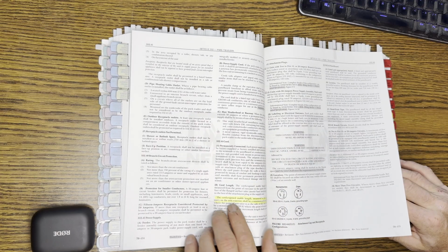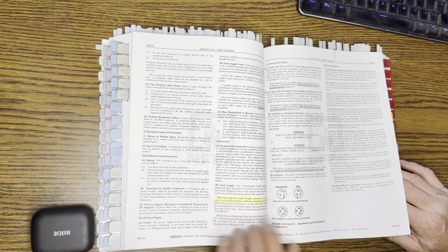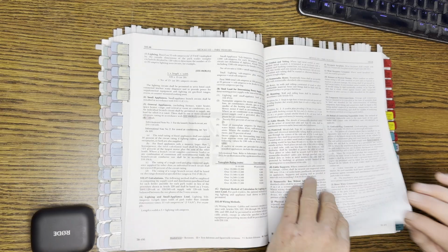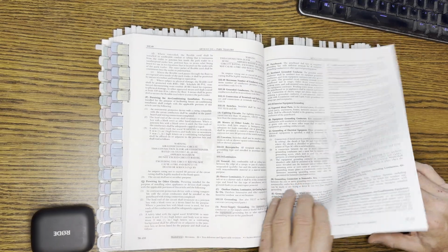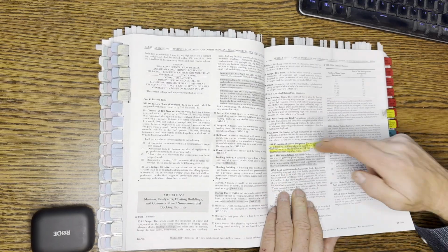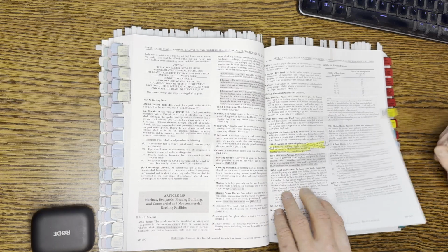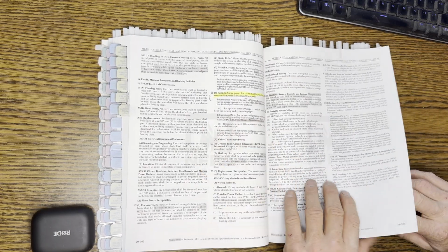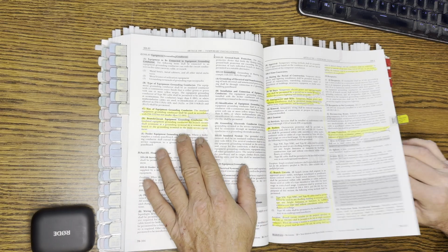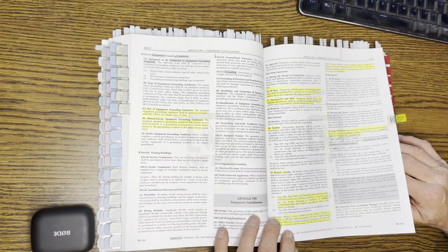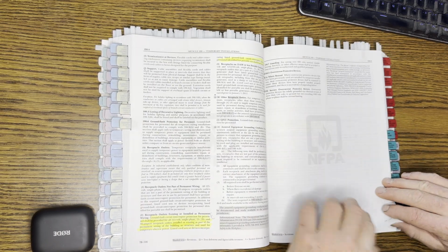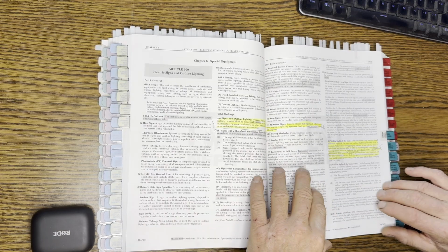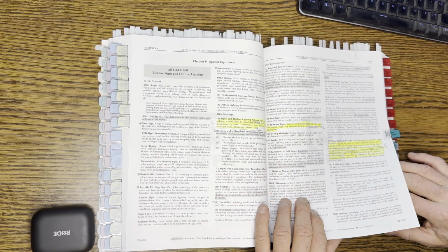It's not really park trailers, but for instance, the length of your service line is going to be different for a mobile home. Your amperage rating is going to be different, 50 amps for a mobile home versus 100 amps for a house. Your boat power is going to have different amps and different lengths and different protections. So there's some overlap between commercial and residential.